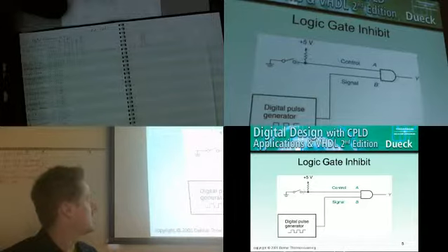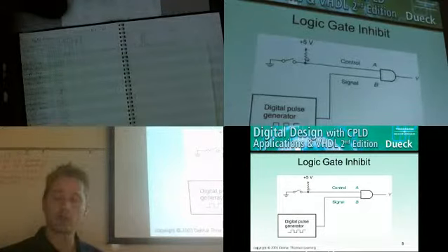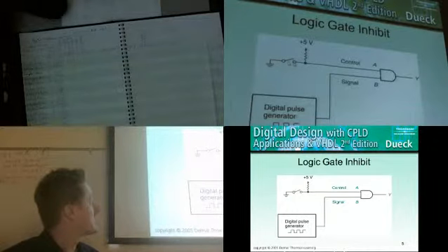Ohm's law and Kirchhoff's voltage law and all the other laws of AC or DC circuit analysis say that because this switch has a much lower resistance than the resistor, which is going to be about 1K or 10K or something like that, the switch is going to win, because you basically have a battle going on here. The resistor tries to pull up to +5. The switch tries to pull down to ground.